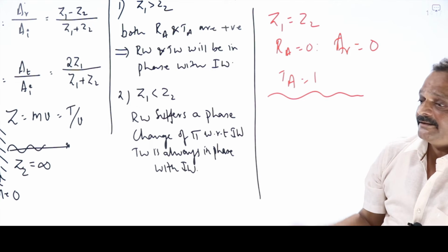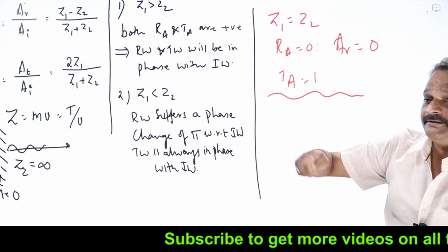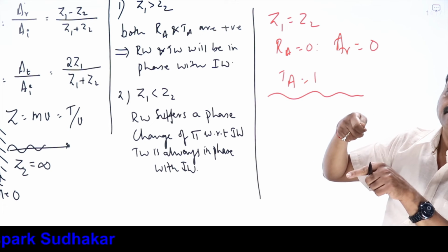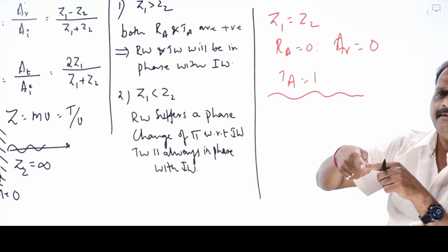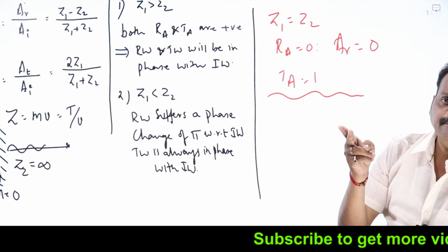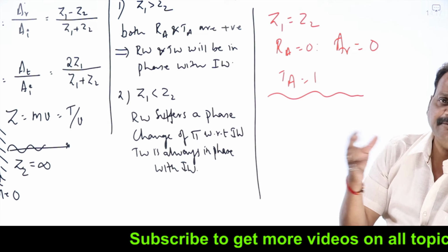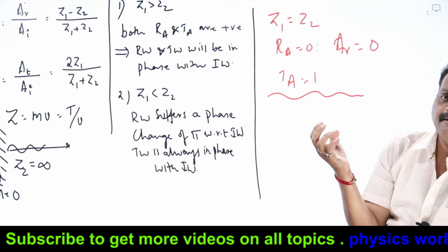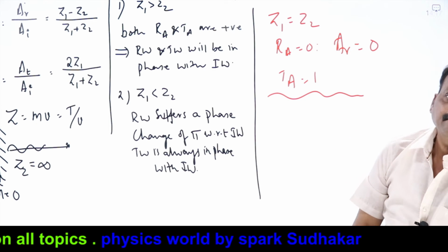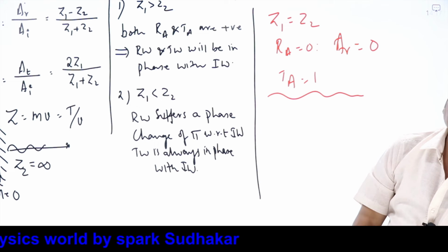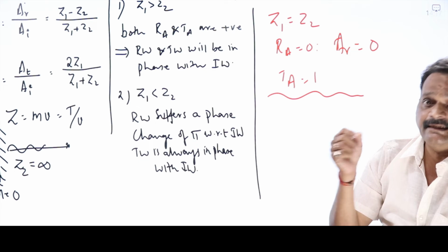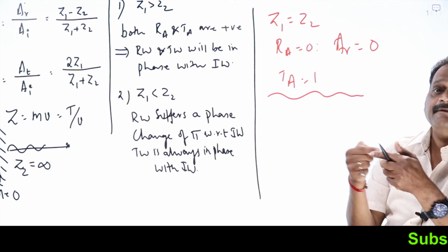Similarly, with our cable connection, the cable person will give a connection to your TV. The output impedance of that cable must be equal to the input impedance of the TV. Domestic TVs all made throughout the world have only 2 input impedances possible, 50 ohms and 75 ohms. Similarly, for our internet connection, the fiber cable will be inserted into your router, and through the router it comes into your computer. The input impedance of the computer must be equal to the output impedance of that cable. That's called impedance matching everywhere.